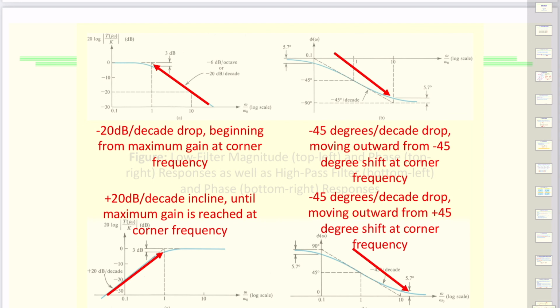Now, given the amplifiers which behave based on the frequency that is coming in, we use internal capacitances in devices, and we use coupling capacitors, which give us many different applications where we want to maintain gain at low frequencies all the way to DC maybe, or maybe we have a signal which is almost constant, or if there is any fluctuation we want to get rid of, like maybe temperature based sensor output changes.